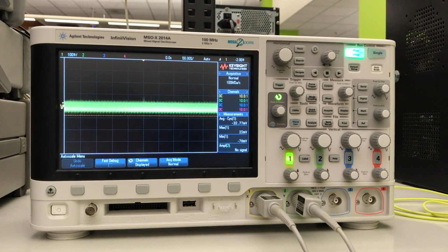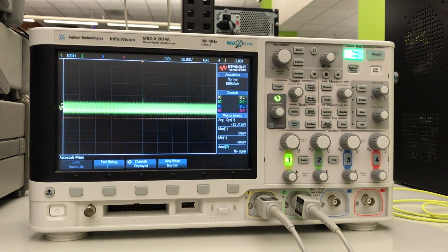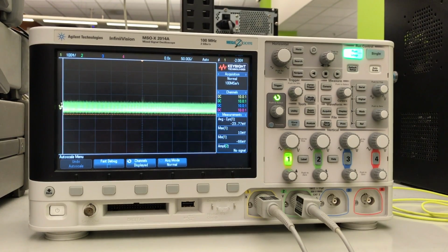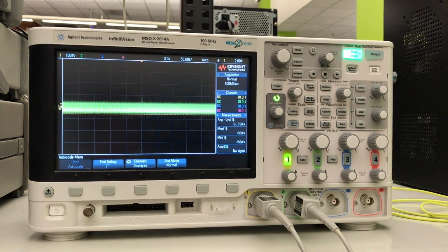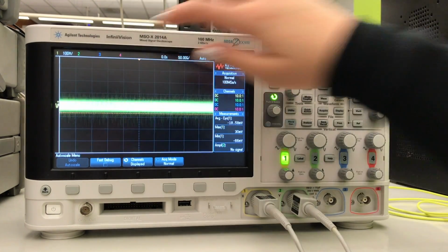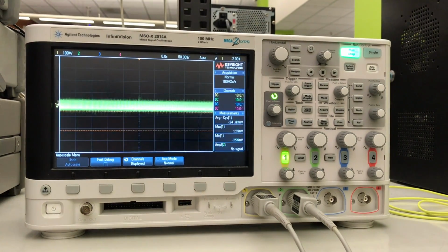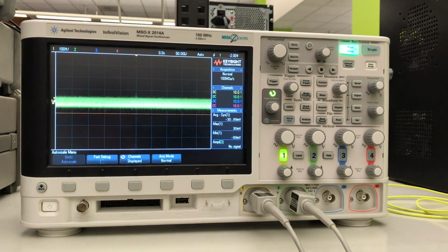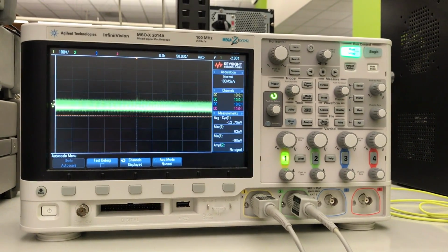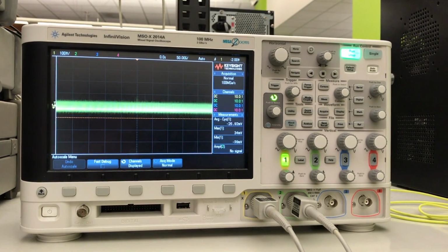The other dimension, in the vertical direction, is used to look at voltage. Again, each little square on this grid corresponds to one little step in voltage. You can see what each step in voltage is by looking up in this corner. Right now, we're looking at 100 millivolts per little square of this oscilloscope screen. As you can see, our signal isn't very interesting right now. All we see is noise.